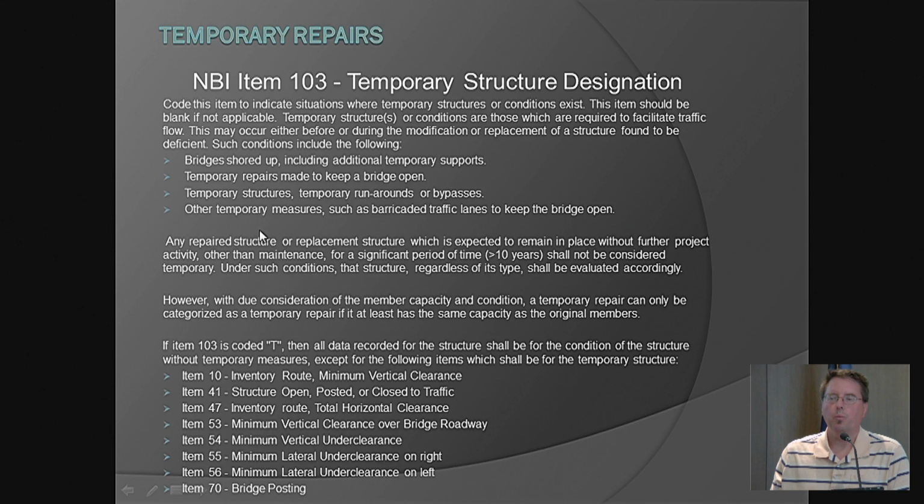So then when the inspector is out there and he's looking at your bridge, say if he gets out there and he notices something has been done to the structure and he hasn't had a chance to talk to the bridge owner, he's going to probably consider that a temporary repair, just as a general rule.